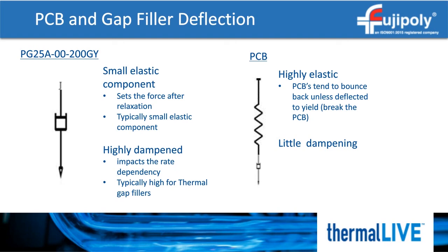All of them are suited for understanding the behavior of different types of materials. We can also look at them in parallel for constant loads to get a better understanding of the creep of an elastomer, while the Maxwell model is better suited for understanding the stress relaxation for a given strain, similar to how a gap filler is used.